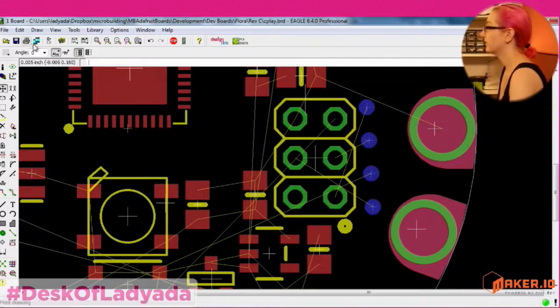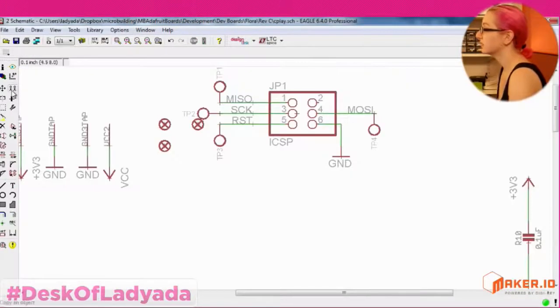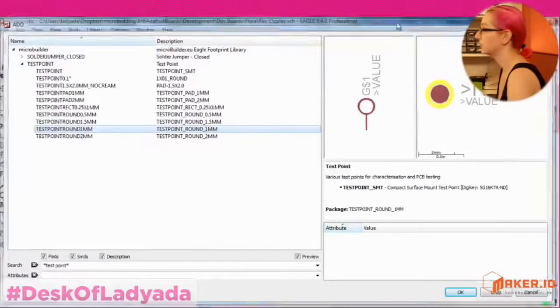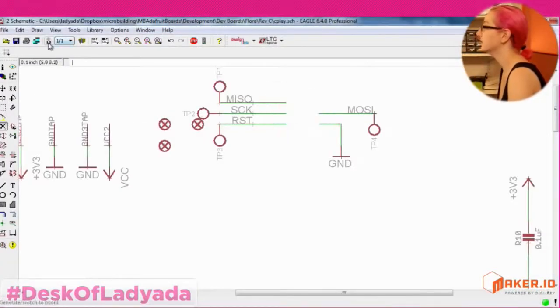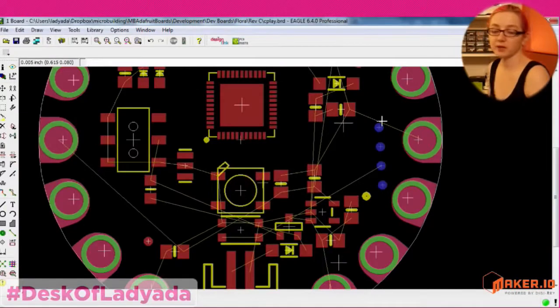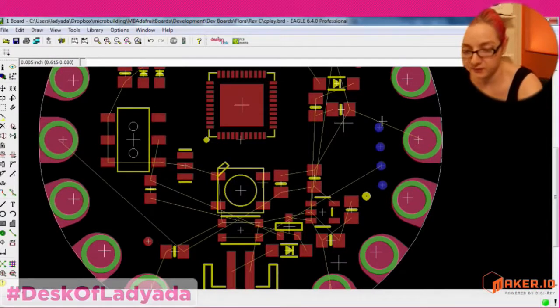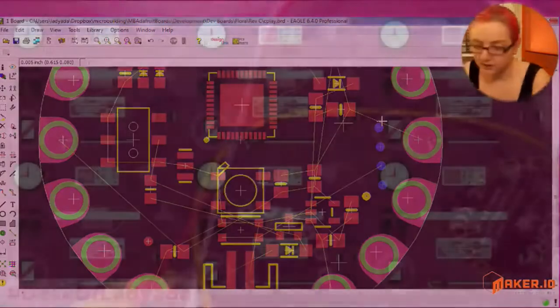And that means that I don't have to have this large through-hole piece, because I'll just use pogo pins, little spring pins, to touch the touch pads. If you look on the bottom of a lot of products, you'll see touch pads. So maybe I'll show the touch pads. Can you go to overhead?